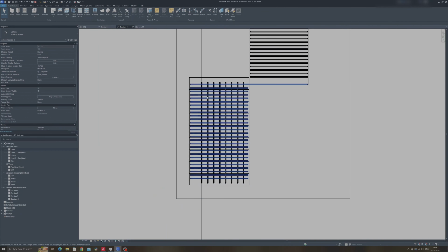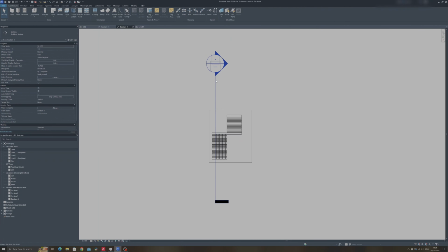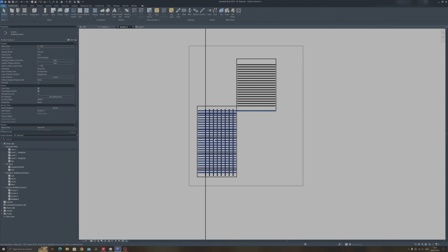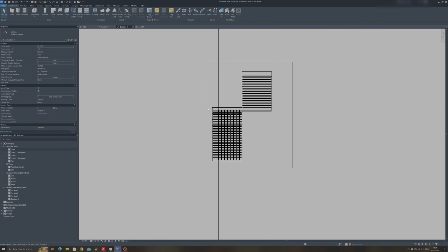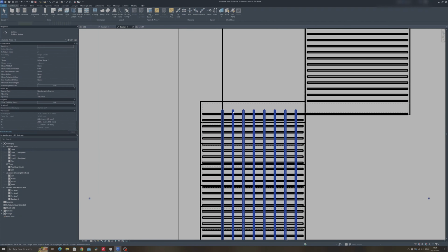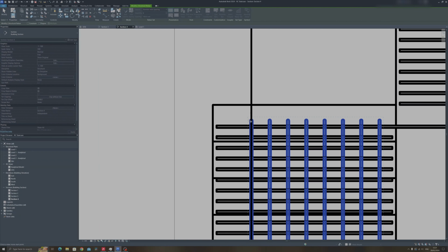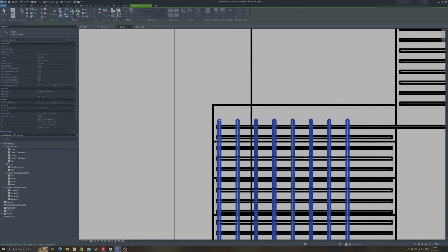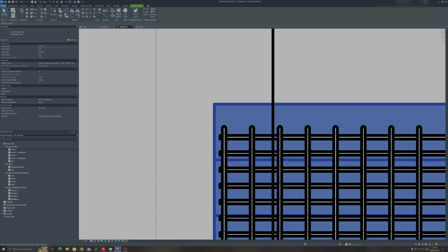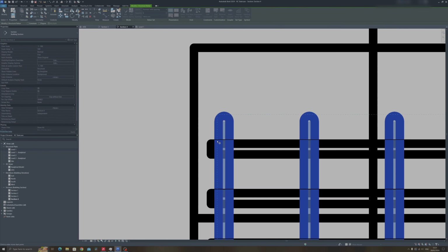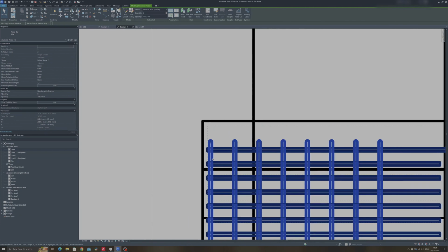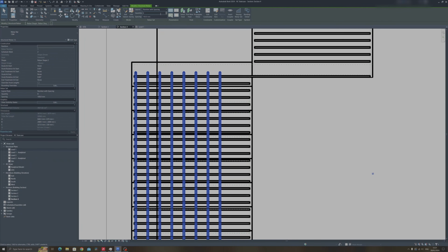So as you can see, the first rebar was placed where section 3 is cutting into the staircase. So if I were to change the position of section 3 such that it is outside of the staircase, then it would be more to the left. So now I'll just manually move it to the left side. I'll move it a smidge more. And we can increase the count to 10.